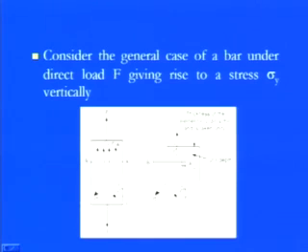So this is my A, B, C. You see this is AB, where we have the sigma y, and we have this BC, which is the plane cutting. So this is my oblique plane, and this is the straight line where we are considering sigma y in the y direction. The thickness of this element in the z direction is thin, because we are considering that no stress is acting on it, and it is taken as unity. Because this is a unit cube, we have to consider a unit thickness, a unit depth, all across this particular structure.